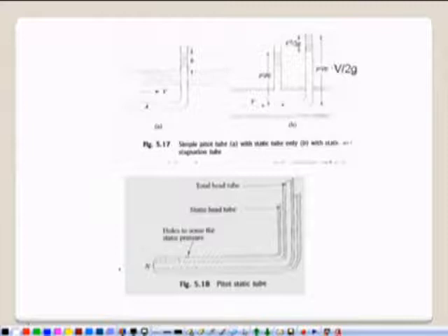Now here we have three figures to understand the Pitot tube further, because this was the device which he developed basically. This is an open channel flow, a flow in a river in which water is flowing, and here pressure is equal to atmospheric pressure. So this is a free surface, and if we have a tube which is tilted in this manner, and this portion of the tube faces the flow, then this velocity v is retarded to 0 at point A.